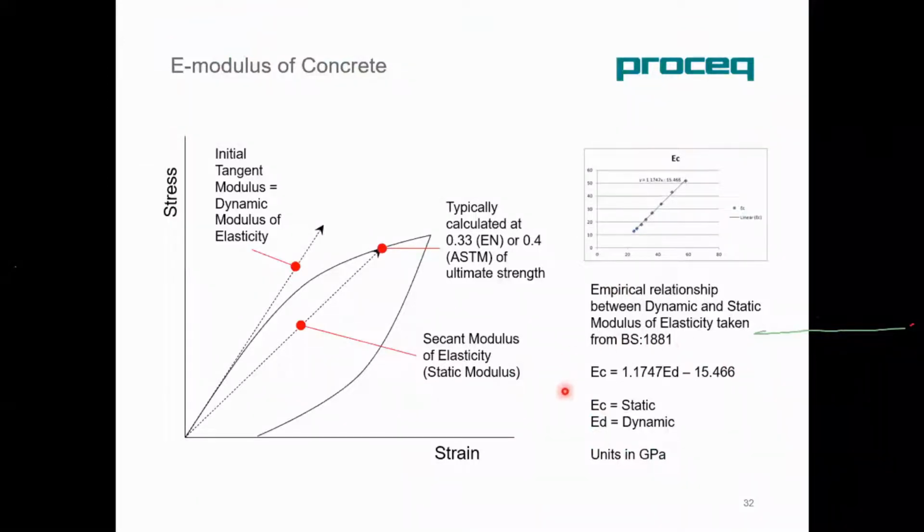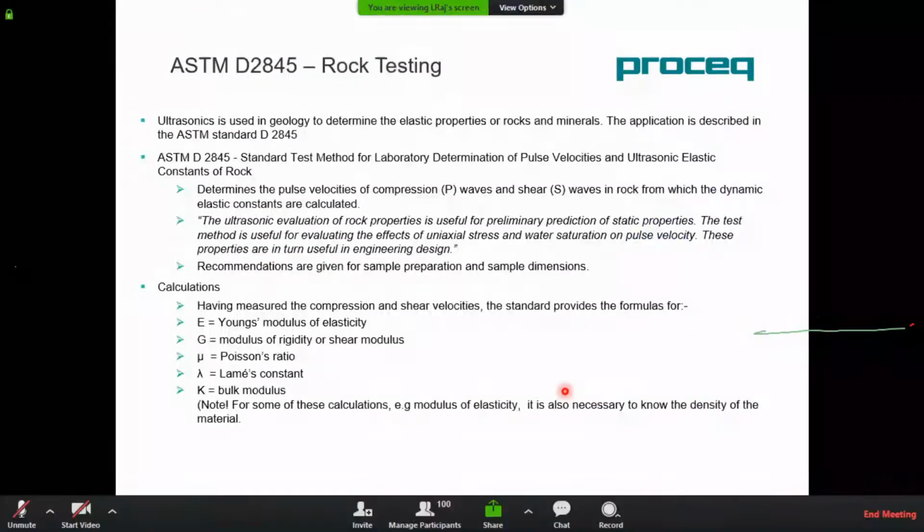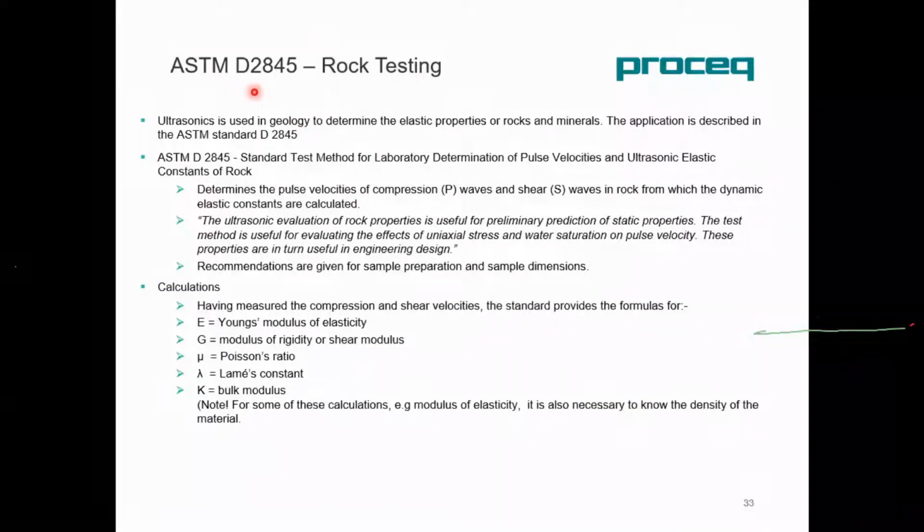Also, if some of you are interested in doing rock testing with UPV, I would recommend the ASTM standard D2845. If you have a chance, please get hold of this standard. It's a very good paper that explains how to go about doing rock testing with UPV.